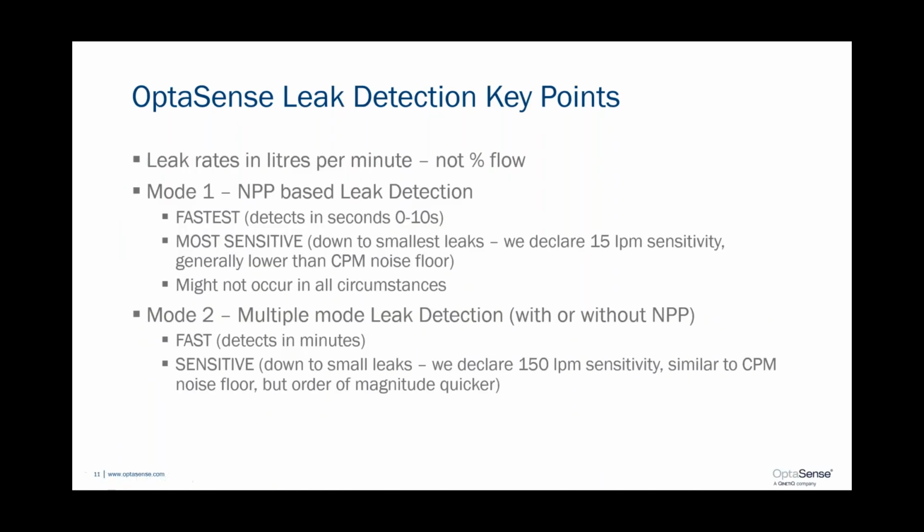So our key points. The leak rates that we're going to talk about will be measured in liters per minute, not percentage of flow. And that's because rather than looking for a change in flow conditions, we're actually looking for a product that's escaping from the pipeline. The bigger the escaping amount of product, the easier it is to detect, naturally.